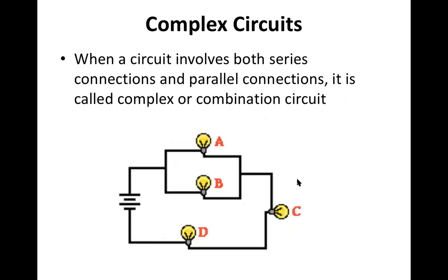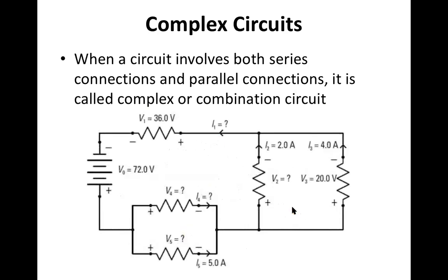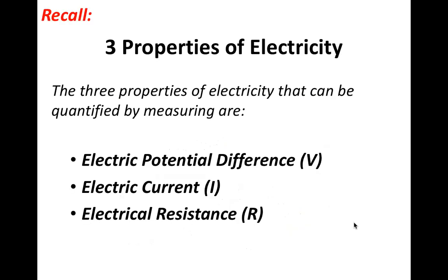More often than strictly a series or strictly a parallel circuit, you'll see complex circuits, and this is the focus of grade 11. So make sure you're putting a lot of time into practice problems with complex circuits. They're also called mixed circuits. So A and B are in parallel with each other, but they are in series with C and D. It's like a parallel circuit within a series circuit. We call this mixed. And then you can get into even more complex circuits, which we will solve for.